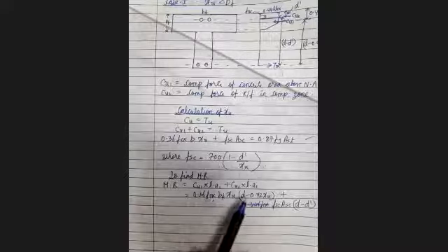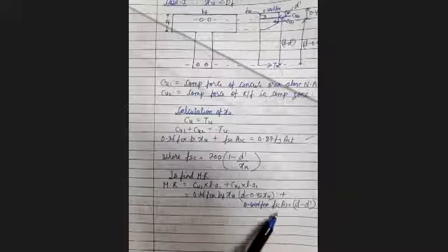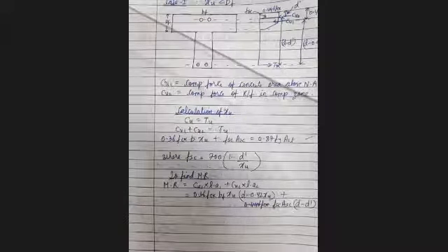So this is the equation for MR: CU1 into lever arm 1 plus CU2 into lever arm 2, where CU2 is FSC into ASC into D minus D dash. Now if I talk about the balanced section for all the three grades, can you tell me what will be the equation for this? This is the general equation for the under-reinforced section. For the balanced section, can you tell me now?